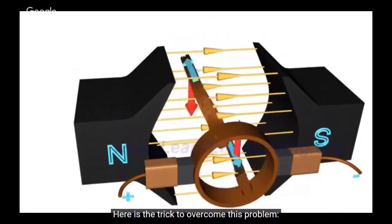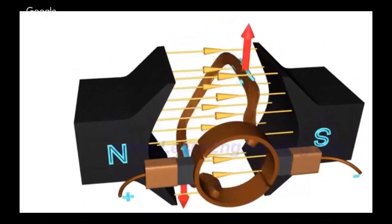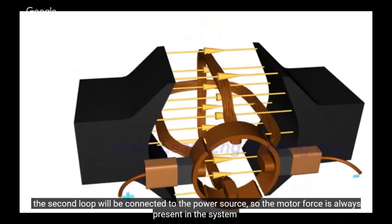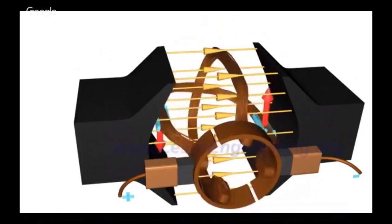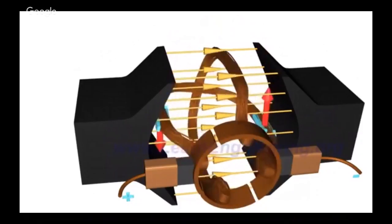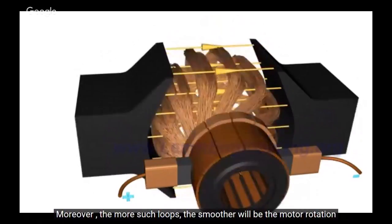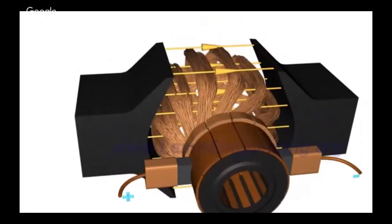Here is the trick to overcoming this problem. Add one more loop to the rotor with a separate commutator pair for it. In this arrangement, when the first loop is in the vertical position, the second loop will be connected to the power source. Force is always present in the system. Moreover, the more such loops, the smoother will be the motor rotation.